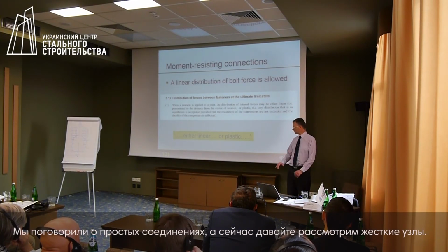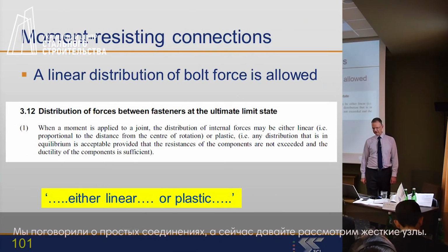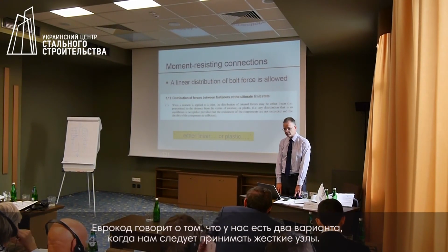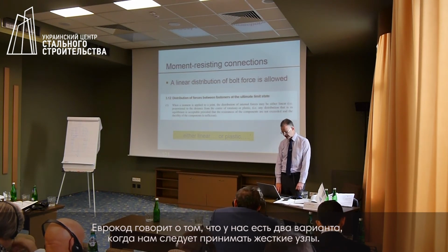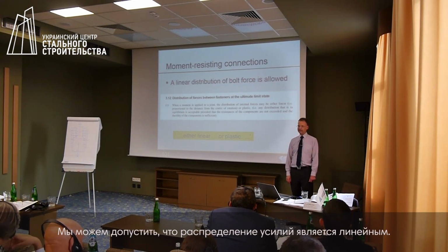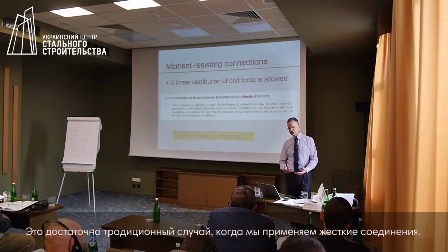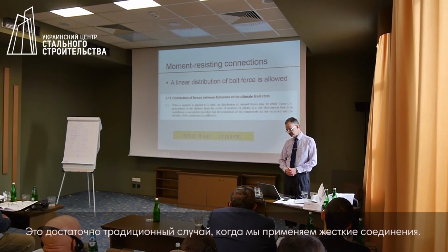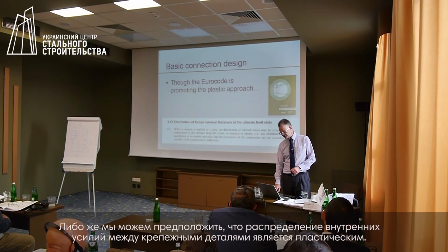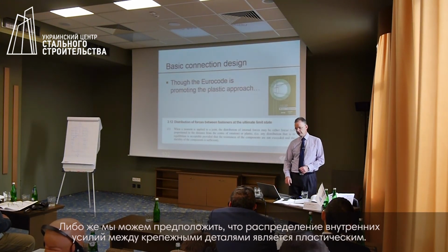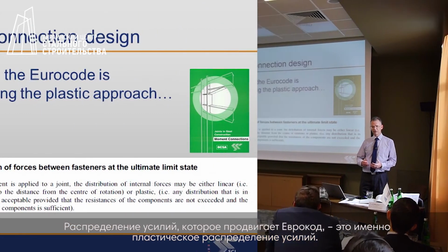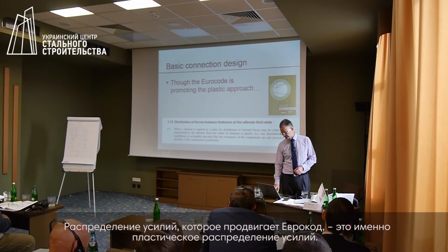So that's simple connections. I'm going to move on now to moment-resisting connections. The Eurocode says that we have two options when we consider moment-resisting connections. We can assume that the distribution of force is linear, which would be a very traditional way of arranging a moment connection, or we can assume that the distribution of bolt force is plastic. The distribution of force that the Eurocode promotes is really a plastic distribution of force.